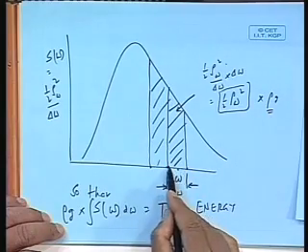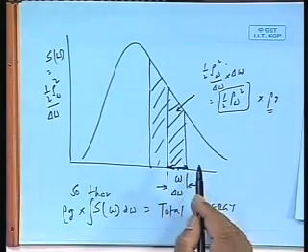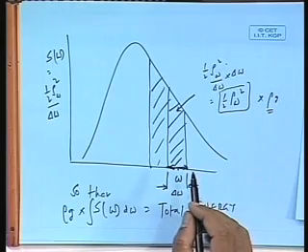So again, if you look back, what we will be doing is we have a spectrum, you do Fourier analysis. So you say that wave between omega 1 to omega 2 has so much height, omega 2 to omega 3 height so much, omega 3 to omega 4 height so much, you are averaging it all out. So now I know that my waves coming between this frequency band, just like when I said there, all the waves coming between this height band 0 to 1 meter occur so many times.